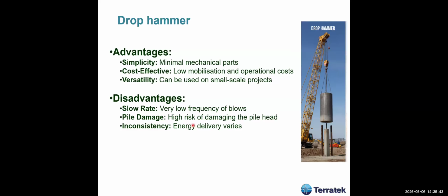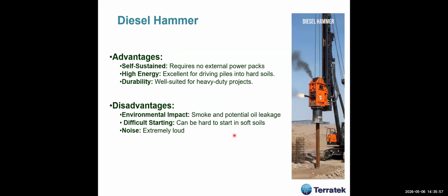Pile damage, high risk of damaging the pile head, especially in concrete piles. And inconsistency of energy delivery, which varies during the project. So small projects, okay, large projects, no way.